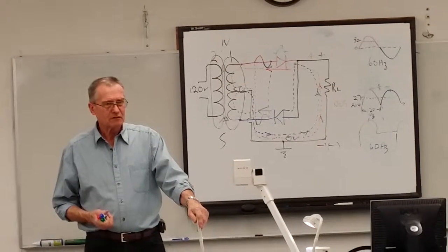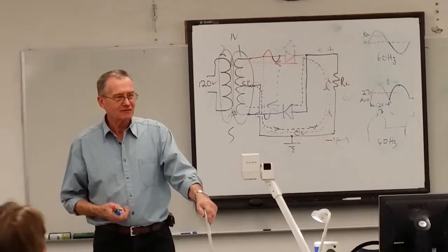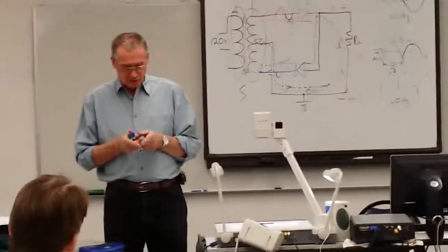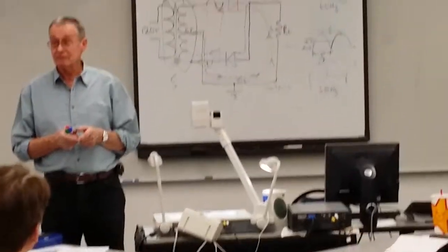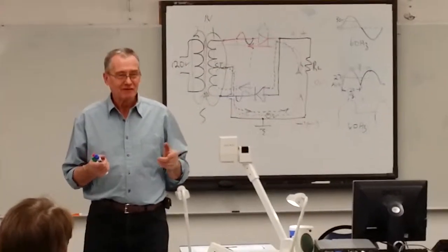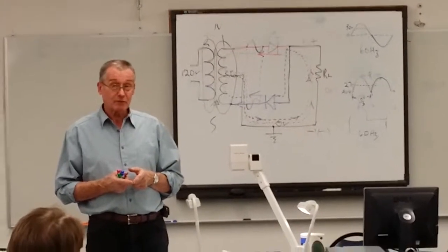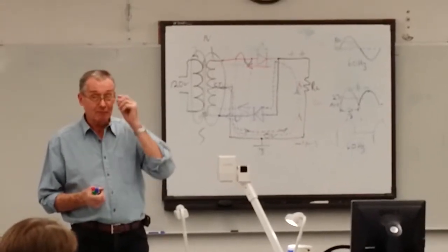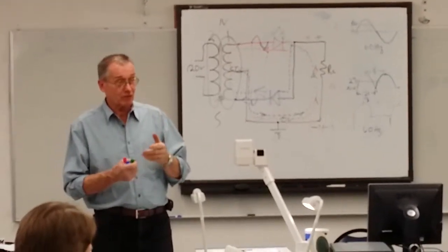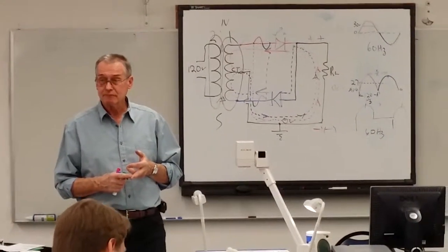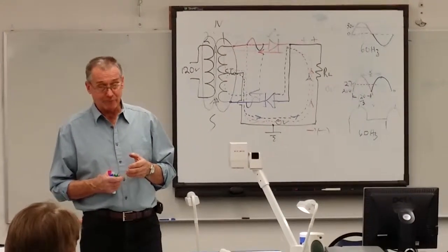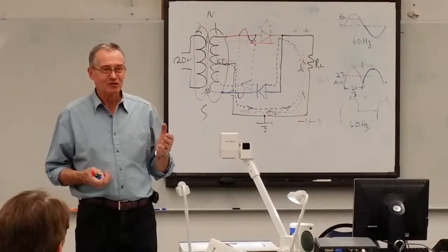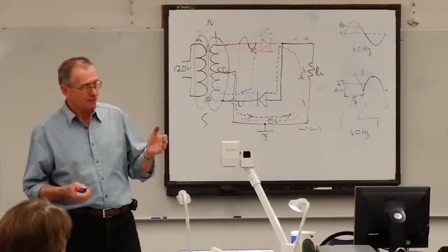You don't need much power, really, do you? But they'll sell you that little box, sometimes more expensive than the toy itself, the little remote control car or whatever. That little adapter has a transformer in there, and it doesn't really need more than one diode, but the more expensive ones will use 2 or 4 diodes. So you can go to Radio Shack and get an adapter for $3, or you can pay $12 and get a full-wave bridge type of converter, converting the AC to DC.